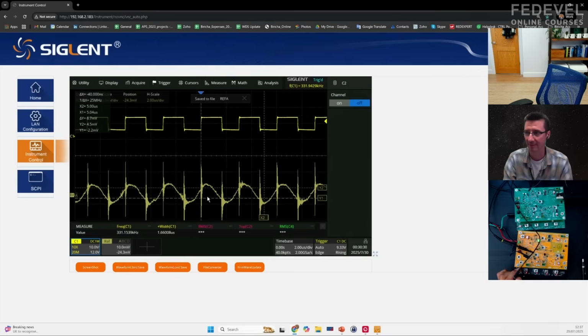right? If you remember again from university physics and engineering lessons, right? The ripple voltage across the capacitor was 1 over C integral of I dt. So the capacitor is integrating the current with respect to time. The current is a ramp. Therefore, the integral of that would be a parabola going up. And you can kind of see it here, right? It's a parabola going up and it's a parabola coming down, but to us looks like a sinusoid. And that's the ripple voltage for a ceramic capacitor.